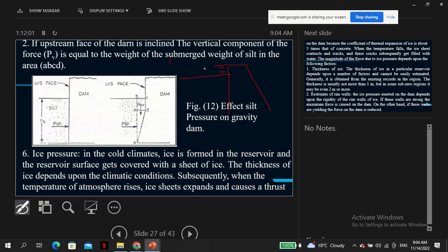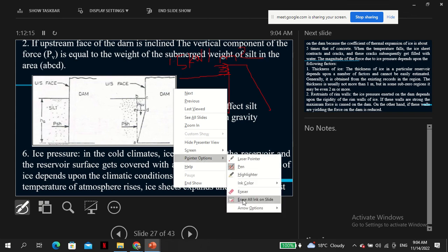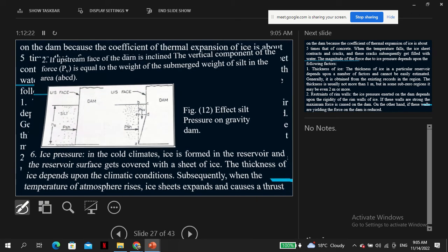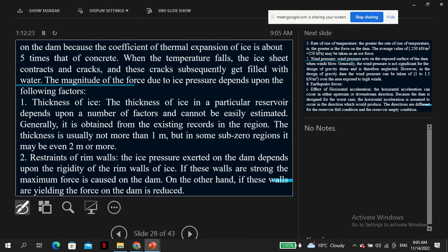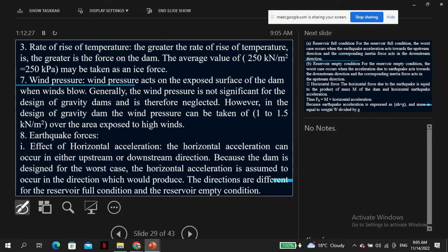But if for some reason you have to consider wind forces, then you take the distribution over the surface as a load of 1 kilonewton per meter squared, for argument's sake. But typically you can ignore it, because the free height exposed to the wind force is very small.